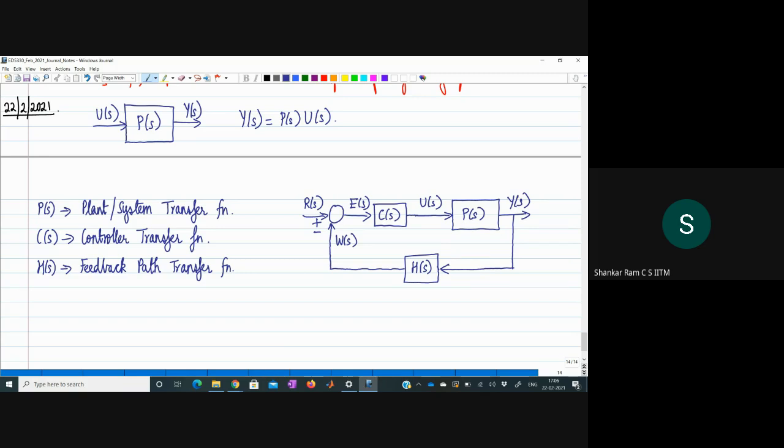So please now observe how I'm writing the equation. As I discussed just a few minutes back, if we have this block diagram representation and we are given the transfer function of a block, the output signal from the block in the complex domain is going to be the transfer function multiplied by the input signal to the block. So that's how we are going to write these functions.